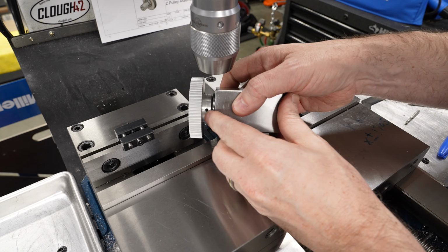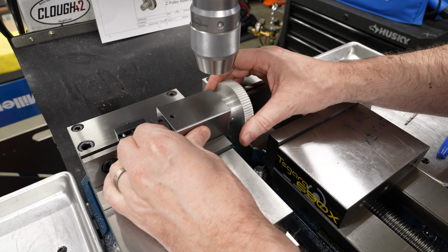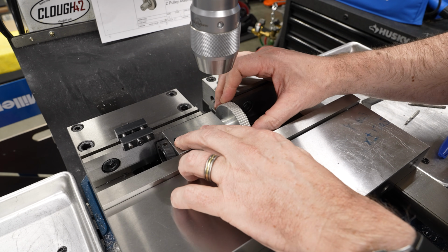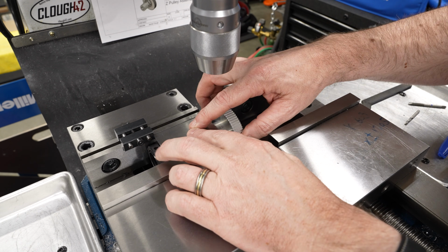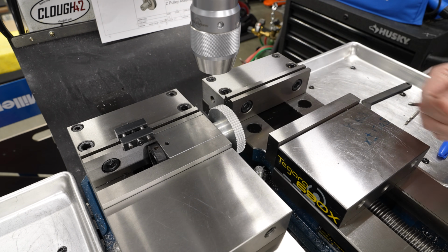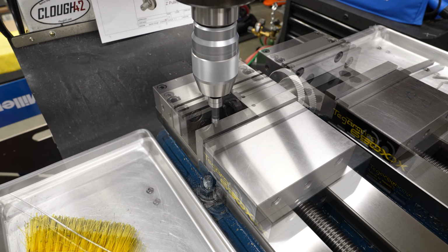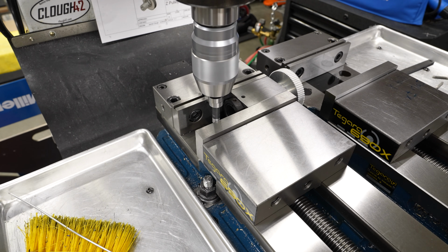To put in the new set screw holes, we've got this mounted in a 5C collet block, and I've got it set up with the existing set screw holes at 90 degrees to the faces, so that the other two screw holes that we put in will be on the other 90-degree points around the circumference of the part. And as you've seen me do many times, I'll use an edge finder on the front and back jaws of the vise.